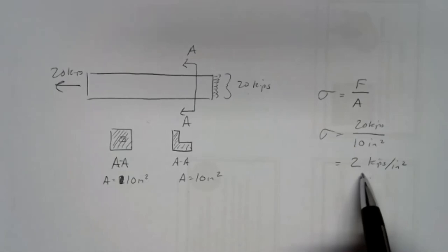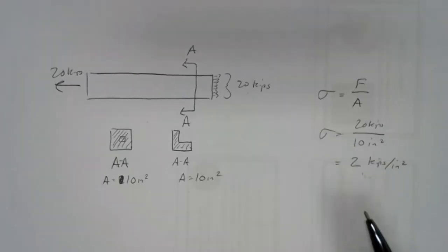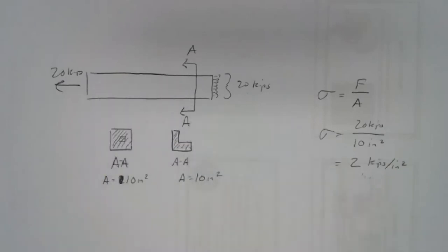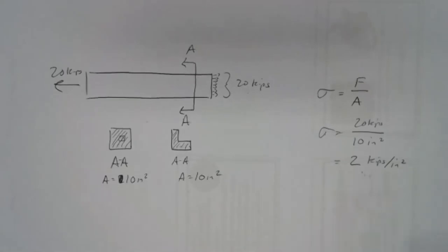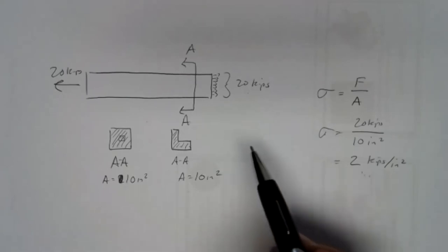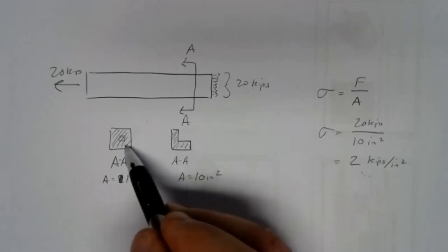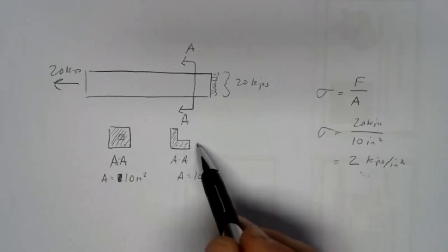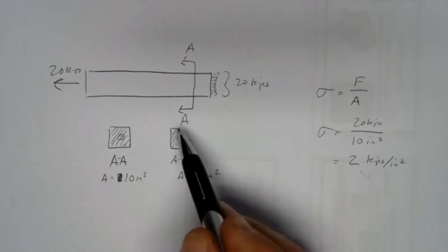The stress that this material will break at only depends on the material. So as long as I know this material is made out of 2024 T6 aluminum, I can go and look up what's the ultimate stress for 2024 T6 aluminum. It doesn't have an entry in the table for 2024 T6 square channel or 2024 T6 angle. I don't need any of that.